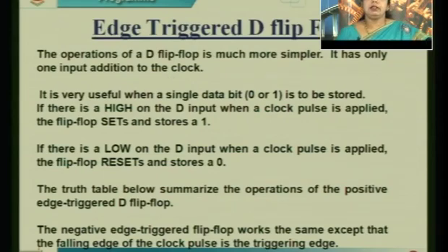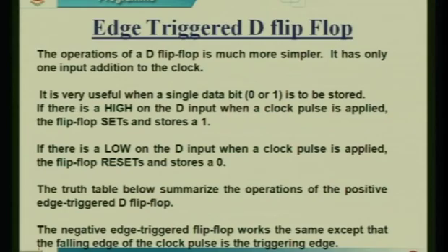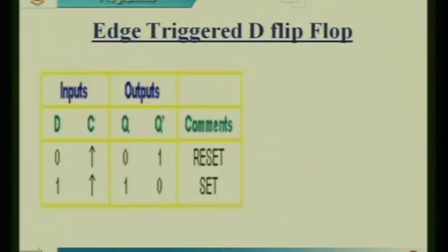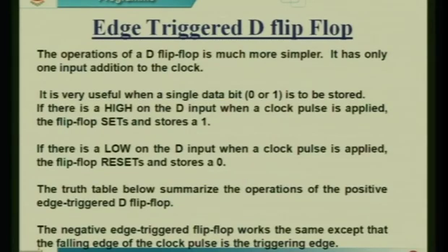Similarly, we discussed the D flip flop in the previous session. As you know what a D flip flop is, how is it formed? We discussed in the previous class that a D flip flop is formed by combining the inputs S and R with an inverter. I am tying this S and R and making it a single input, and that becomes the D flip flop. So I am shorting this single input to S and R, and that becomes D.